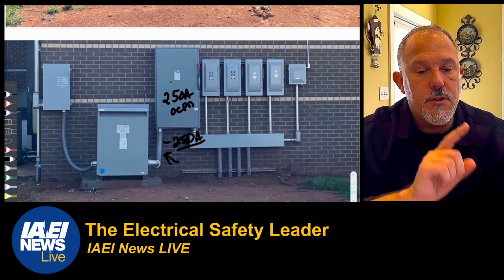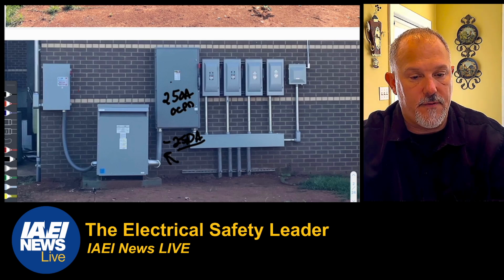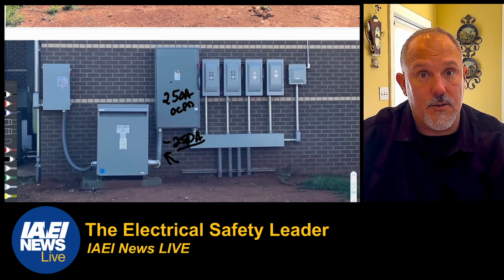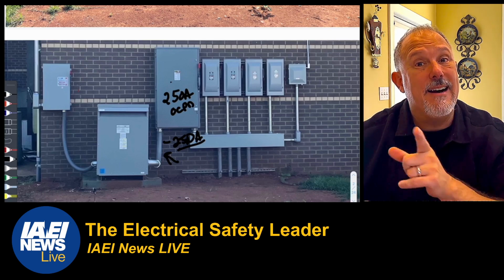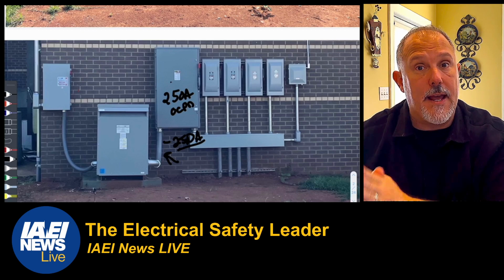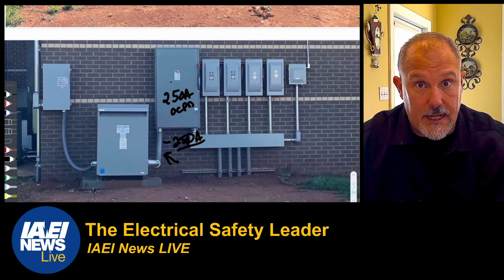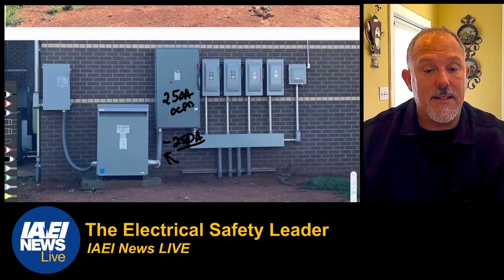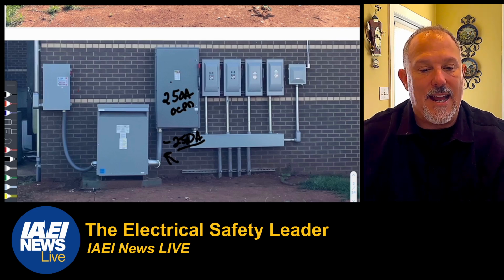Those conductors cannot be less than the rating of the equipment containing an overcurrent device supplied by the secondary conductors. So if this was a 250 amp disconnect switch, fusible disconnect switch, or 300 amps, whatever we selected, remember we can go as high as 300 amps, then the ampacity of that conductor cannot be less than that rating of those overcurrent protective devices and that equipment. Not less than the rating of the equipment containing an overcurrent device supplied by the secondary conductors, or not less than the rating of the overcurrent protective device at the termination.